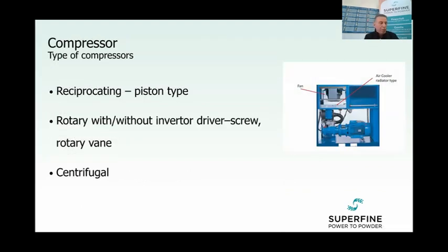Okay, types of compressors. The basic working principle of an air compressor is to compress atmospheric air, which is then used as per requirements. In the process, atmospheric air is drawn through an intake valve. More and more air is pulled inside a limited space mechanically by means of piston, impeller, or vane.